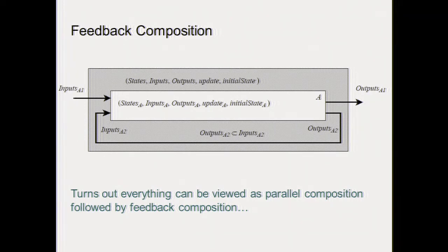It has to be written exactly like what I say. Otherwise, you cannot claim a priori that the things work. By the same token, if indeed the block in there is a finite state machine of type Moore, this always works. If it is a machine of type Mealy, not necessarily. You may or may not have a well-defined composition.